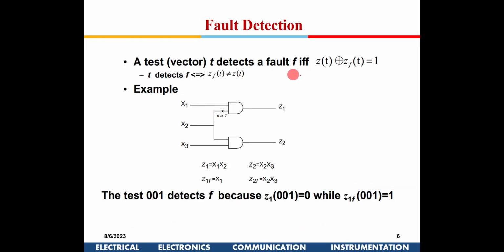Now coming to today's class, see what fault detection is. If I give a test vector, the actual output without a fault and with a fault should be complements, right? Only that. Suppose I have a stuck-at fault 1 out here. Now if I have to identify that, the test vector should be, sorry, I have to give 1, I have to give 0.